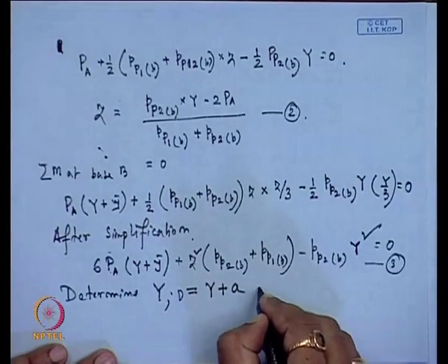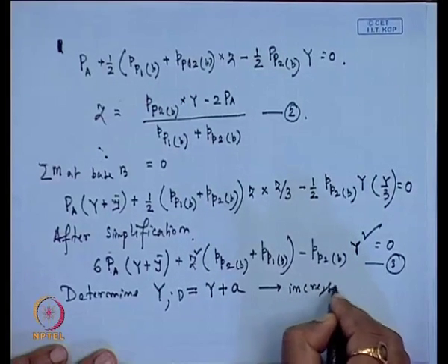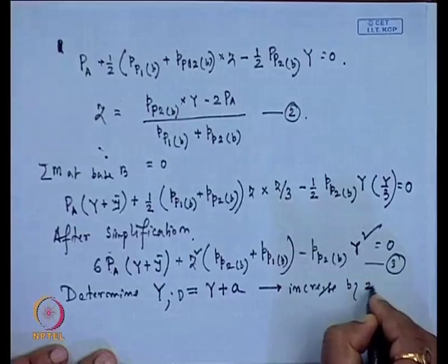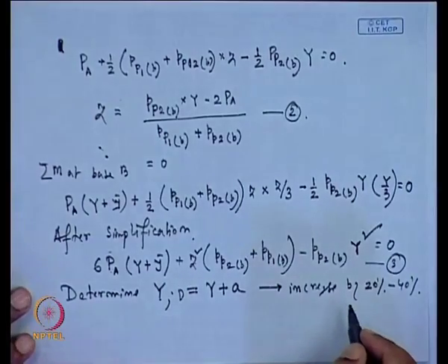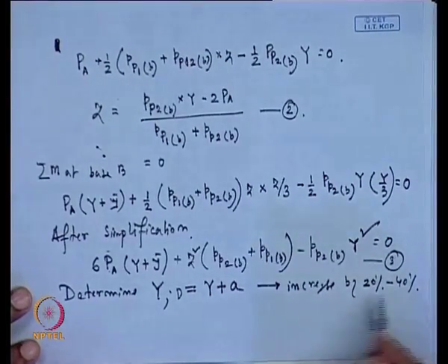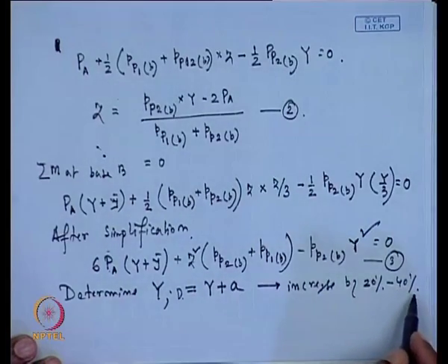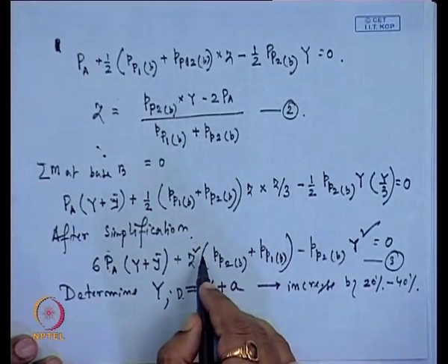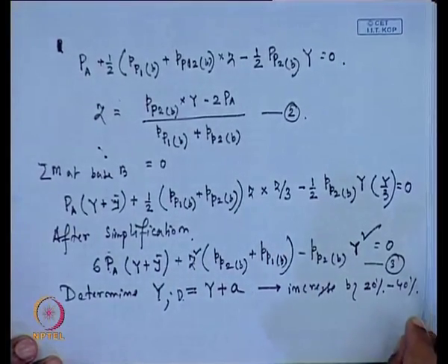Now, once we get these things, you have to increase this D by 20 to 40% to give an additional factor of safety. For this factor of safety purpose, we have to increase this D by 20 to 40%. In this fashion we will get the depth of sheet pile based on the calculation from these 3 expressions, and this is for the sandy soil.